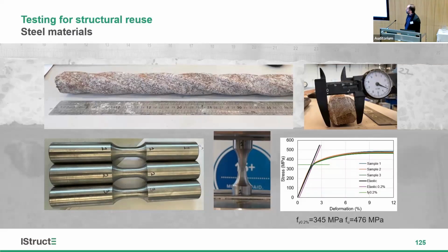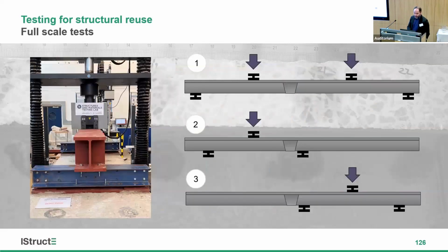We extracted the reinforcement bar after the test. This is how it looks. The 35 millimeter twisted bar. Of course, we had to fail the slab first and then remove the reinforcement. We didn't remove and then test the slab, which would probably have been much easier for us. Then we extracted, because it's very difficult to test anything of this size in any machine, some coupons. The reinforcement characteristics were very similar to what appears in the standard that gave the qualification characteristics for the rebar. Now we moved on to the full-scale tests.